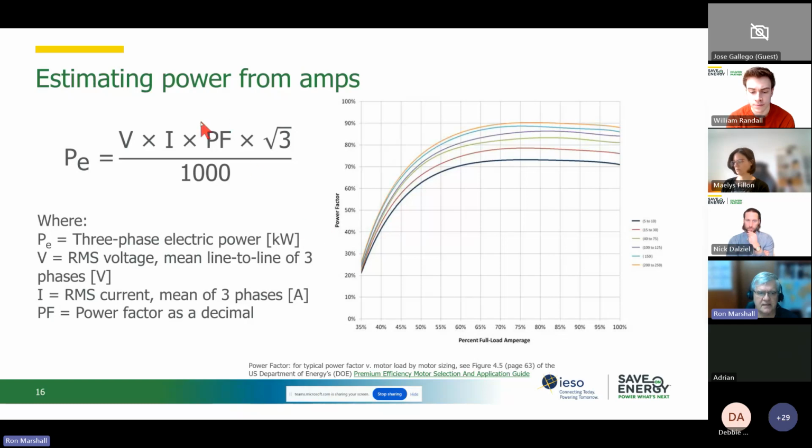If you're assuming, say, the motor nameplate says 85%, if you're assuming 85% for all that significant unloaded power, you'll be making a significant error in your calculations because an unloaded compressor doesn't have an 85% power factor. The power factor might be as low as 20-25% in that unloaded condition, depending on the size of the motor and the load on it during unload power consumption.